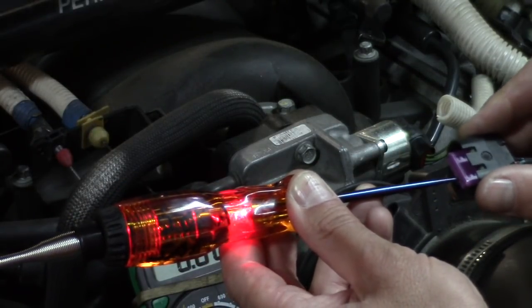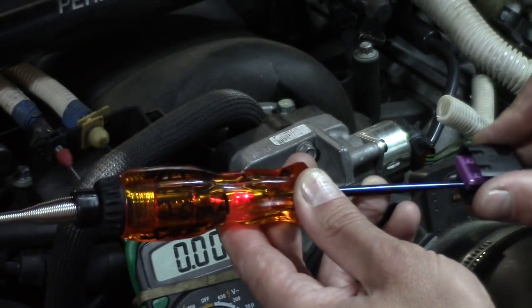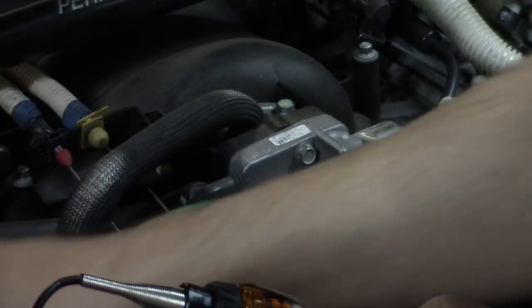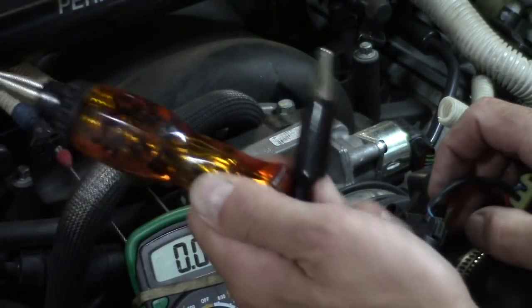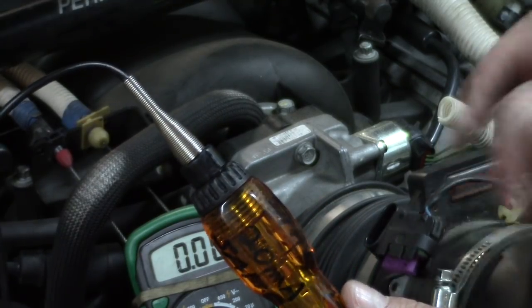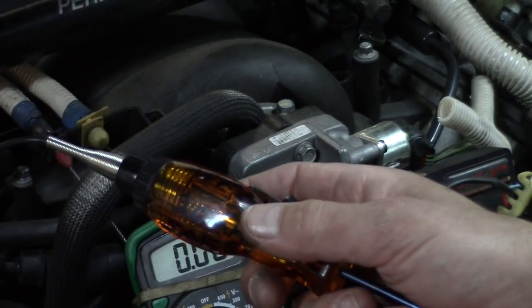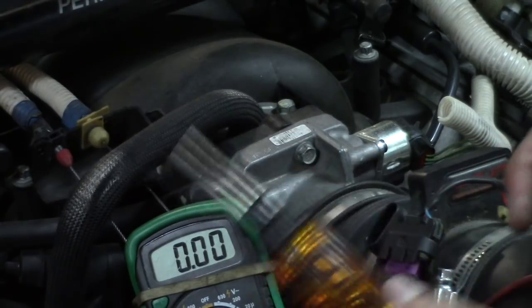So that's indication that I've obviously got my 12-volt power. It does light up a little bit with the 5-volt reference, but it doesn't indicate the amount of voltage you get. I could, of course, also switch my test light over to battery positive and test a ground that way. Not one of my favorite things to do with this test light. I'm safe doing that. This is a computer safe test light, but you've got to remember again, if you're not aware of what you're doing, or you're using the wrong equipment and you're actually jumping that 12 volt through the ground, that's going to be a bad idea. But with this test light, that wouldn't be a concern. We certainly could do that.